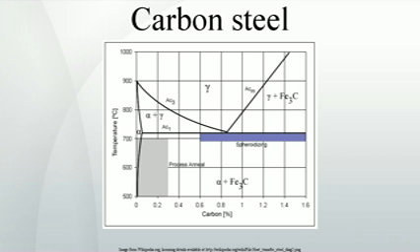This results in a coarse pearlitic structure, which means the bands of pearlite are thick. Fully annealed steel is soft and ductile, with no internal stresses, which is often necessary for cost-effective forming. Only spheroidized steel is softer and more ductile.